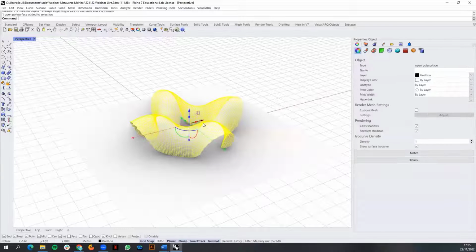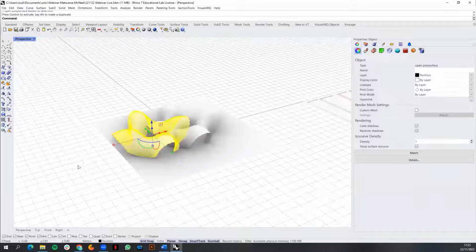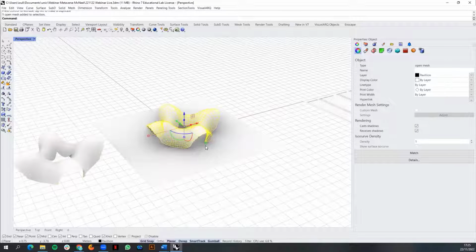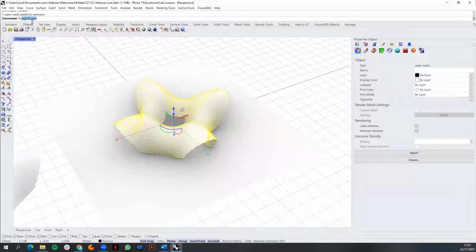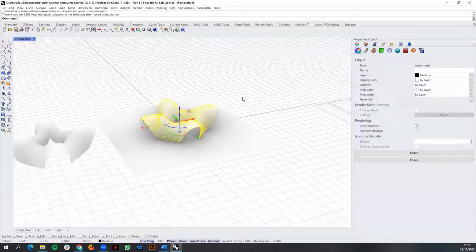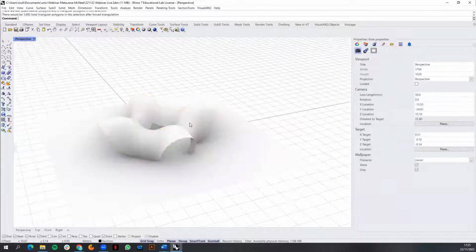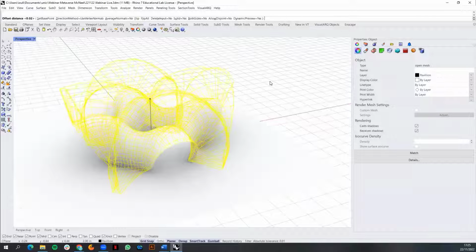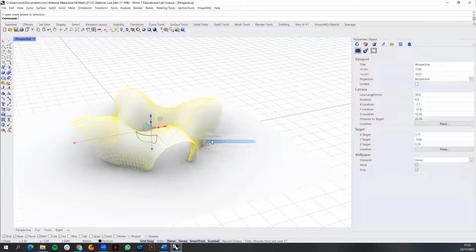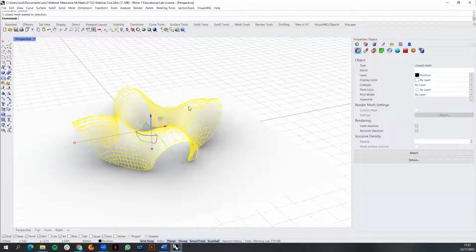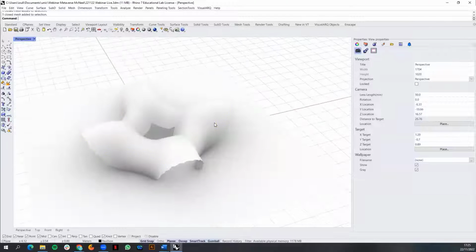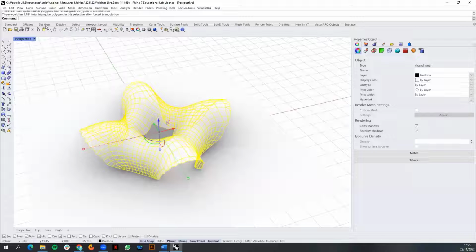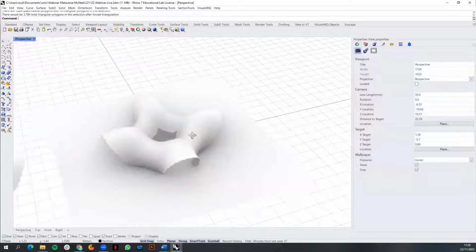So now I have my first surface, and now I have it go through the new mesh. So the new mesh, if we count it now, is about 1,692 triangles, which is much, much better, and we can still do a lot with our scene. So as I said before, I still want to offset my mesh and make it a solid. And I have now a mesh with a thickness, which should be a little bit more than double if I use the polygon count. So yes, I have now 3,784 triangles, which we are good to go.